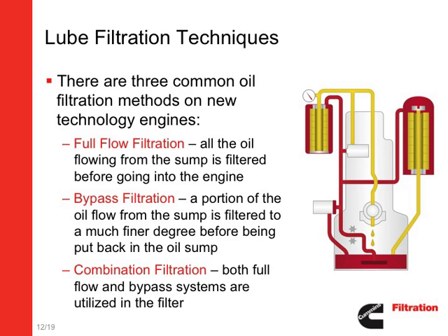It's not always enough, however, so bypass filtration was invented. By diverting a small portion of the oil flow away from the lubricated engine components, a steady stream of oil can be super cleaned and returned directly to the engine sump. Over time and through turnover of the engine sump, the super clean oil contributes to improved oil cleanliness. The result is reduced engine wear rates and longer operation at peak performance levels. The third technique, combination filtration, utilizes both previous technologies in a single system.